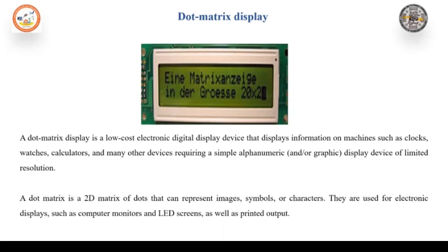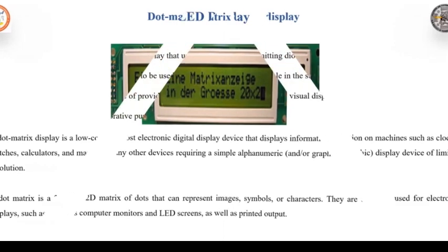Similarly, when columns 11 to 15 are being driven, the data to the ROM is from input buffer 3. After all 3 characters have been driven, the sequence repeats. If the repetition rate exceeds about 20 Hz, a flicker-free array of alphanumeric characters is obtained.